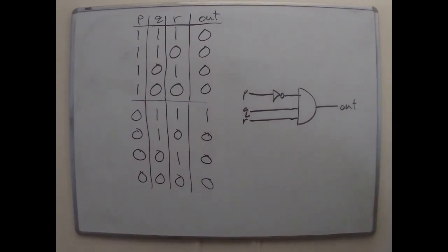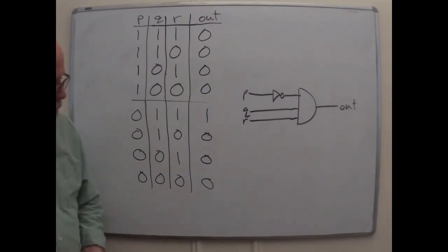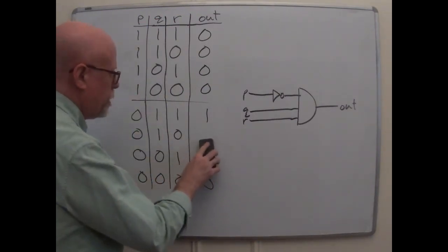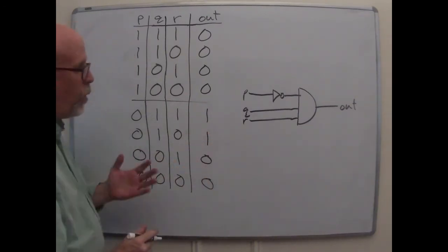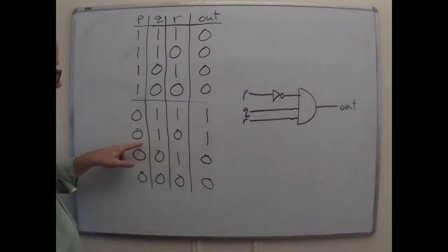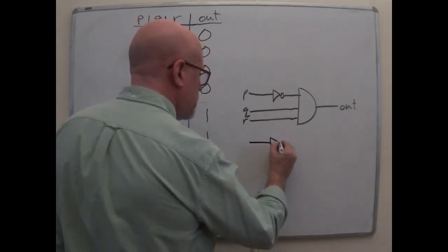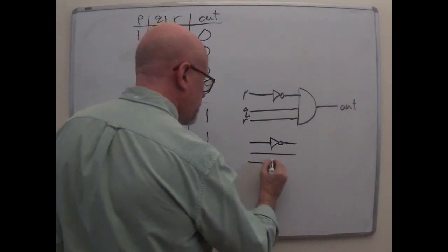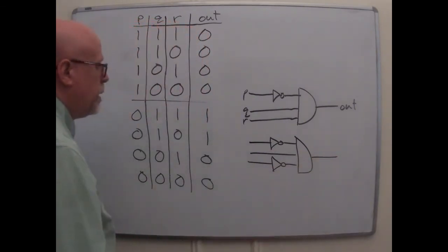Cool. So this is going to give us the output table we want. Great. Now, what do you do when you have multiple spots that you want it to be on in? And instead of a single thing, multiple things. Well, let's do that with a simple example where I want that to come on as well. The reason I want to do this is I've already built half of the circuit I need. What I also need now is to recognize that row. That has 0, 1, 0, so I need not, nothing, and another not. So this would recognize the other 1.